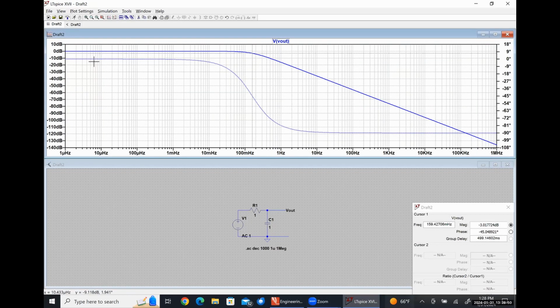The dashed line is how the phase angle changes. So the left axis is what's going on with the bold line, and the right axis is what's going on with the dashed line, right? So effectively, we can see that for very low frequencies, our gain of our system is 0 decibels, or effectively 1. And then once we go beyond that cutoff frequency, it begins falling off at a rate of -20 decibels per decade. So down here at this point, which looks to be about probably 1.6 kilohertz or so, just ballparking here, our gain is -100 decibels.